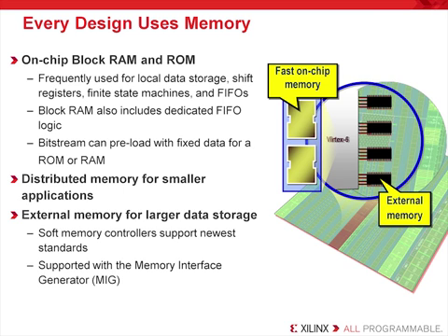Xilinx also includes distributed memory resources which are often used for shift registers, small data storage, ping-pong buffers, and other small functions. Virtex 6 also supports easy construction of memory controllers, which allows you to integrate an external memory controller inside of your FPGA. The Memory Interface Generator, or MIG, allows you to build memory controllers that support the newest standards and supports large data storage applications. This allows the FPGA to be flexible and quickly evolve to meet customer needs of a particular application.